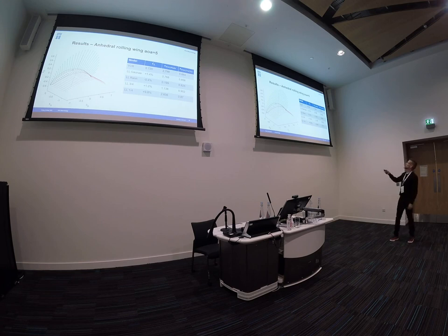But if you take this situation and try to analyze the wake from that with the Trefftz analysis, you get something that's way off. And this is just to show you cannot use Trefftz analysis when you have a maneuvering thing. But still, overall, the new implementation of the lifting line seems to be nice.